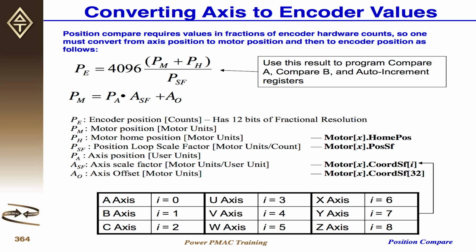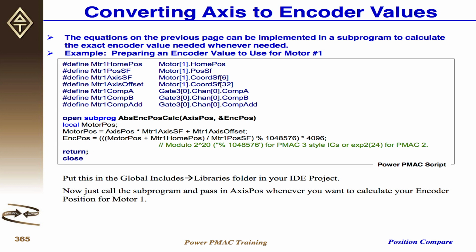So I suppose a comprehensive one would possibly have multiple different scale factors all included in our equation, but the stuff we're going to be doing is just going to be quick linear, motor 1 controls the x-axis kind of stuff, so we only deal with one scale factor at a time. Then we finally have the axis position, which is your user input, and your encoder position, which is going to be your output. So rather than trying to run through all the calculations every single time, we decided to try and automate this a little bit for you guys.